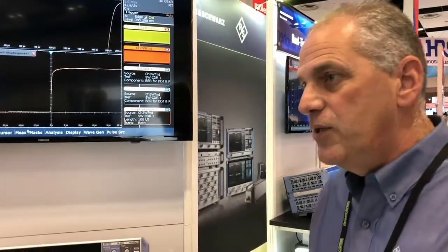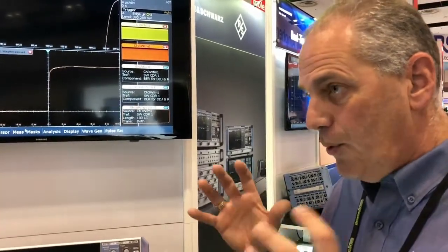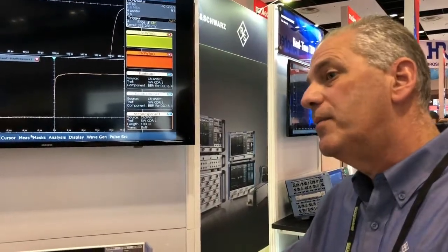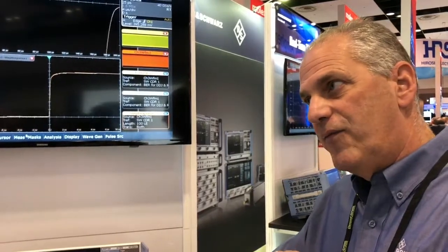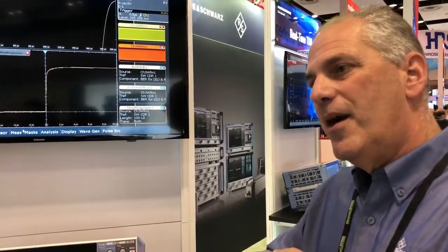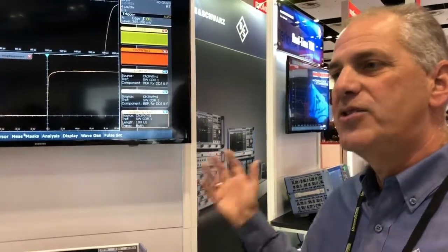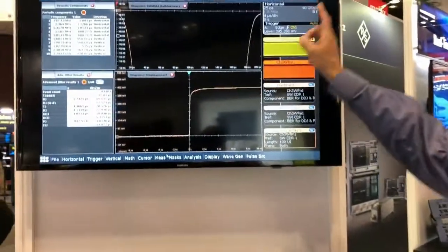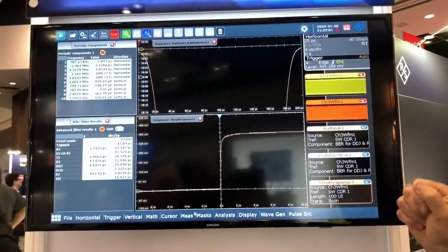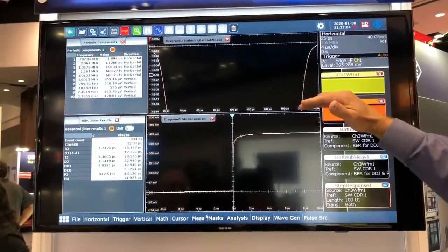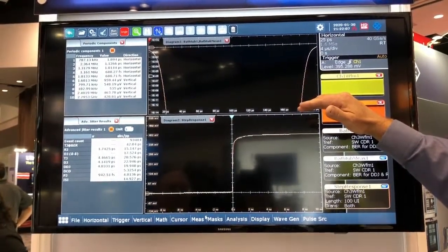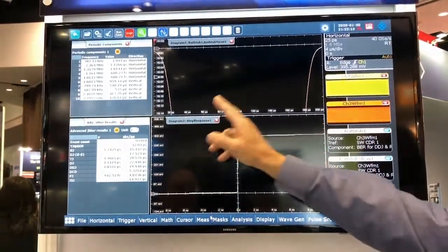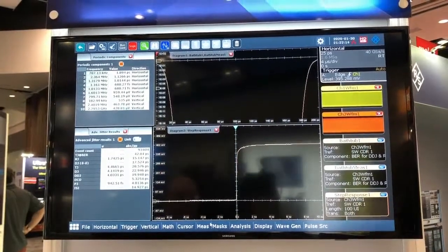And so then what we can do is we can break down the total jitter by adding up those waveforms and essentially measuring the jitter on that modeled waveform. So we're no longer looking at the data from the scope, we're looking at the model, and now that we have a model, I can measure the jitter for any time I want, as large a set as I want, because I've got the entire waveform model. And that's what this bathtub curve shows you. It's essentially the jitter versus sample size. Sample size can be seen vertically. We express it in terms of bit error rate. 10 to the minus 12 is the standard, which means a trillion bit interval would have this much eye opening from here to here. That's the opening of the eye in horizontal dimension.